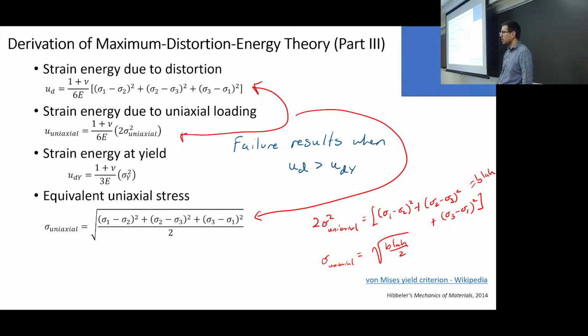Yeah. This is not answering your actual question, but by uniaxial, you just mean that all of the stress is only happening on one axis, right? It's the equivalent uniaxial. So yes, this is essentially exactly the tensile test. It goes back to the bar. A lot of things today, and the last couple of days, we're going back to our basic understanding of F over A for a bar. So there's one normal stress, and all the rest of the stresses are equal to 0.